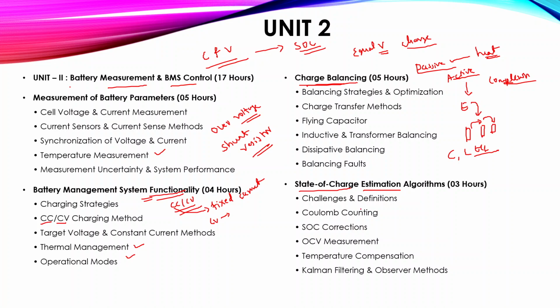Now coming to the state of charge estimation algorithm. We know that SOC indicates the remaining charge in the battery as a percentage. One common method we are going to use is Coulomb counting, where current is integrated over time.